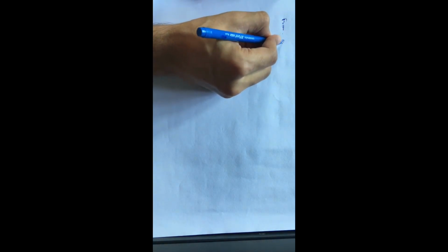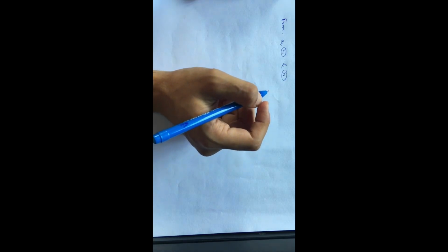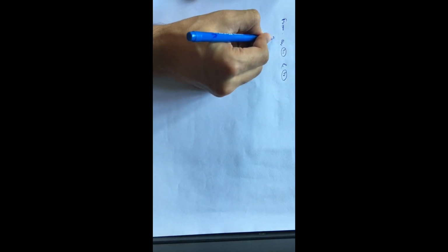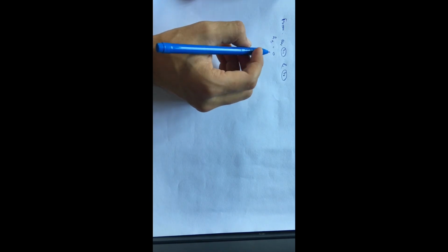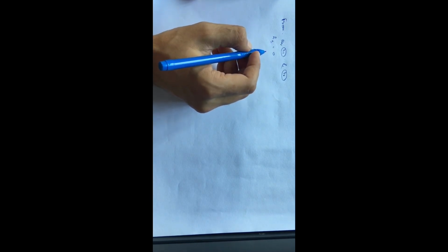Now similarly, from equation 3 and 4, first we considered V2 to be 0 to determine H11 and H21. Now from equation 3 and 4 we are considering I1 to be 0 in order to determine H12 and H22, which are the parameters of the hybrid model.